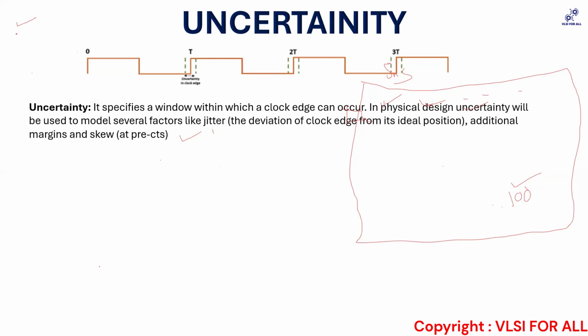Why max delay? Why min delay? Have you ever thought about it? Anybody giving any terminology specific to anything would have given it thought, correct? I think, ma'am, for a setup, if maximum delay is taken into account and the setup time requirement is met, then it is applicable for minimum also. So I think max is written.